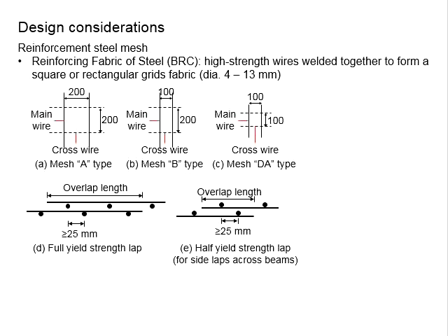Based on the design in the Eurocode, the spacing of the reinforcement bar can even reach 450, depending on the conditions. However, normally the local practice would like to go for a bit more conservative design. Some inherited the understanding from BS 8110.